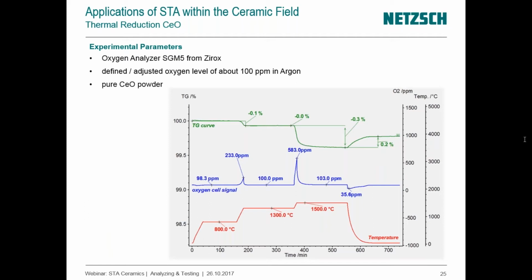So typically, you could go for more stable oxides, maybe, which would be yttria, also yttrium oxide. There would also be the possibility to go to other types of ceramics like boron nitride or magnesium oxide or cerium oxide. Unfortunately, I'm not completely sure right now what will react with lead oxide. So we must have a look. I will cover this and then maybe send you an email afterwards.